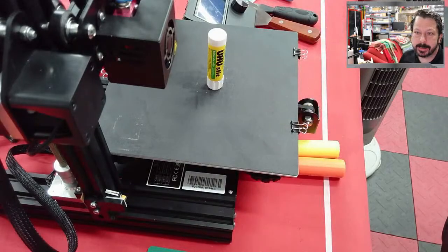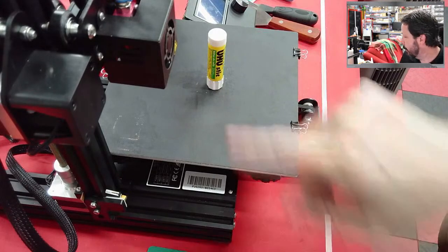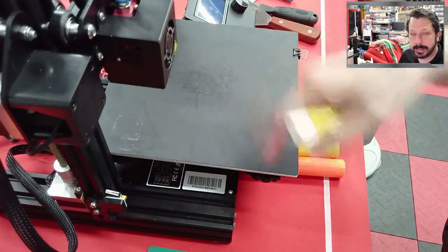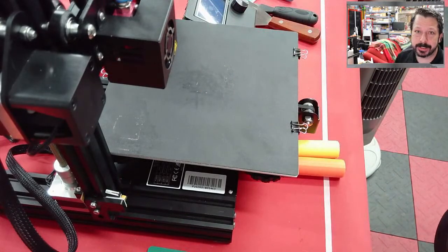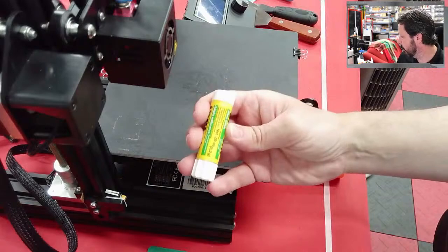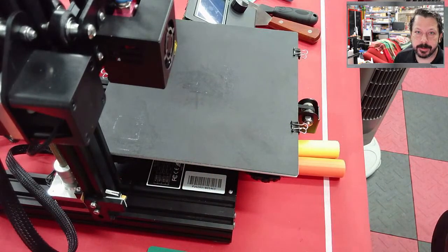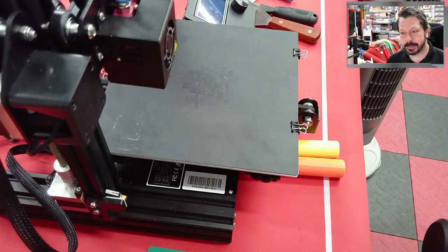I usually do that when the bed is in its heating phase, before you start printing, but if the bed is already heated up, I usually put some glue stick in the area where it's going to lay down the print, and that glue stick will help release the print also. It does clean up with water. These are just regular PVA glue sticks, nothing special, and so you can get it off of there, and one coat will last for multiple prints. So those are different things that you could do.